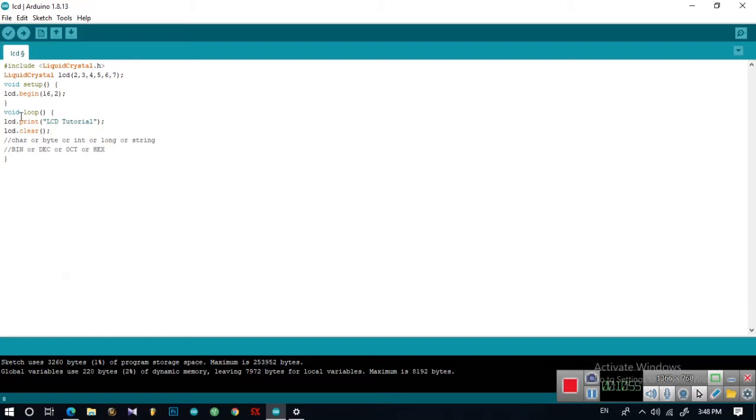And let's go for the next command. It's lcd.home. What it does, it positions the cursor in the upper left of the LCD, which is 0 and 0. And you may ask, what's the application of this command? It's for when we want to show subsequent text to display in just one character of the LCD.